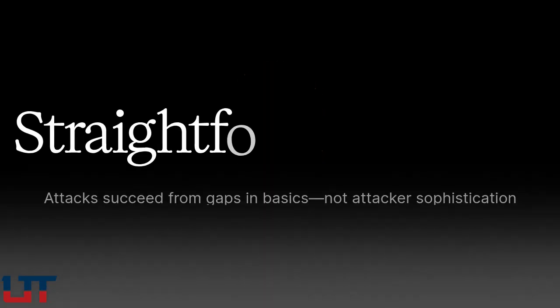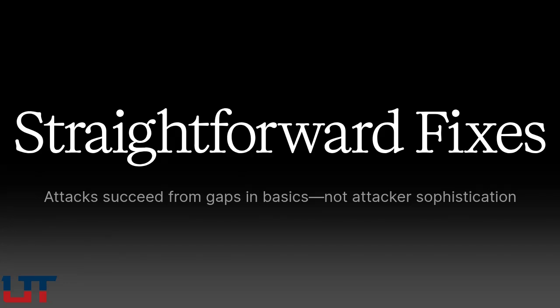Internet-exposed RDP with default credentials is one of the most documented initial access techniques in ICS incidents. The fix is straightforward and well known, and the fix has been available for decades. Attacks of this type succeed because the straightforward fix isn't applied, not because the attackers are sophisticated.